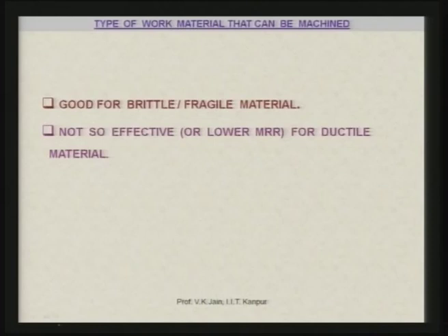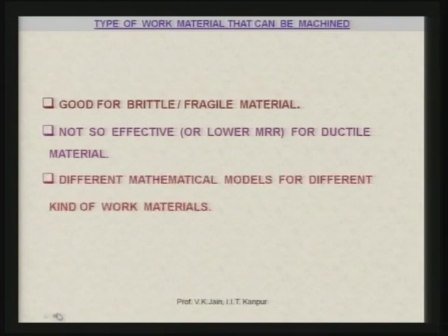This particular process, the AGM process, is good for brittle or fragile materials. It is not so effective or not so good for ductile materials, although it can be used, but it will give you a lower material removal rate.